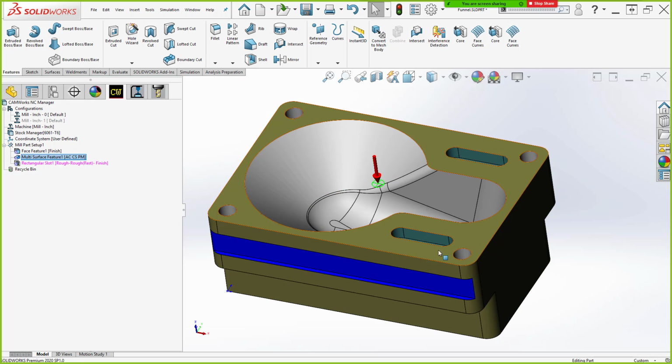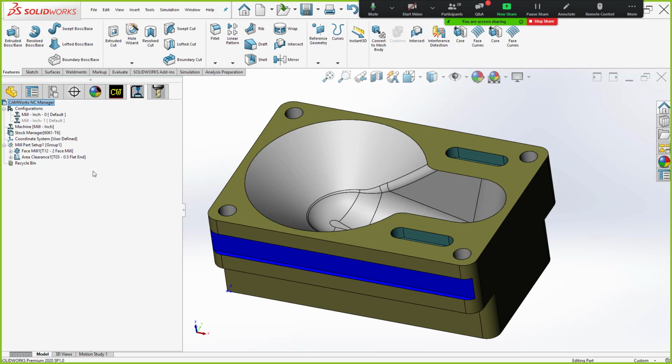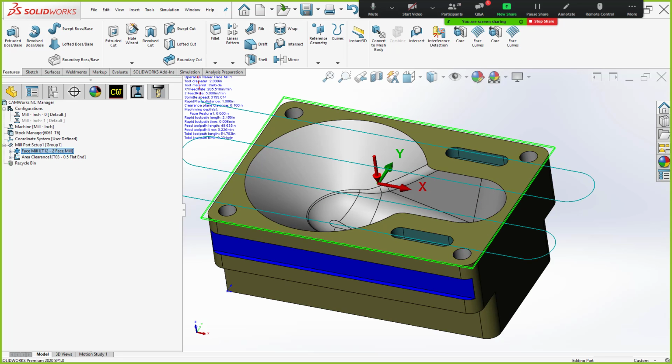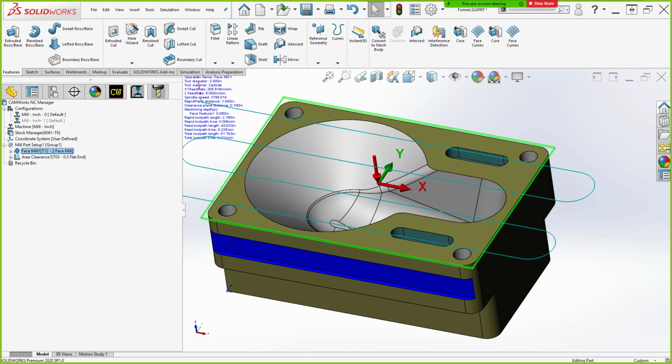Sorry, multi-surface feature, quick way to define it. But if I go and add toolpath to an all displayed, right? Yeah, James, fixtures are the same thing with configs there. You would just have to go re-identify them. It works exactly the same. Fixtures, you just treat it like another CAM file with new fixturing in it, identify fixturing as is, and go for it. All right. Multi-surface feature, all displayed.